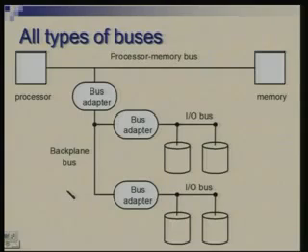So these things could be sequenced in some way, right? Whether they are interleaved at the byte level or at a packet level, or group of bytes level, depends upon how you organize this bus. It may be that this adapter collects several bytes and puts them as a burst on the bus. This one is also collecting its own bytes, and when it gets a chance, it puts its own packet on the bus. So the key thing is that if the bus has a higher capacity, it should be possible to put things in sequence and interleave them in some manner.